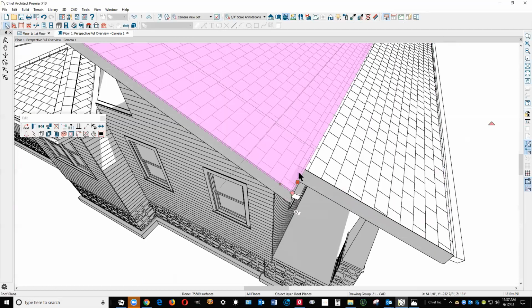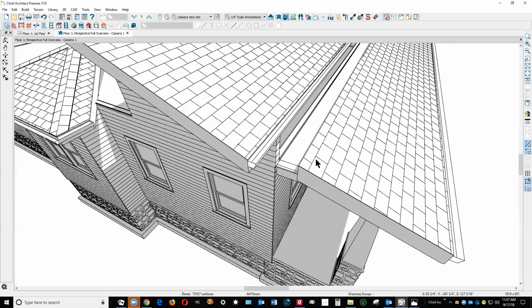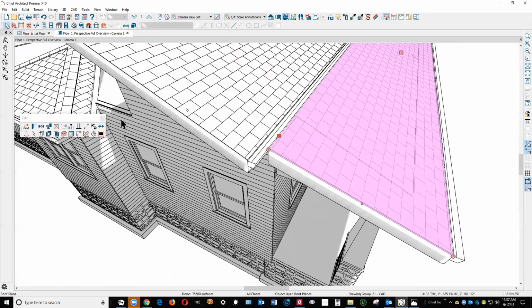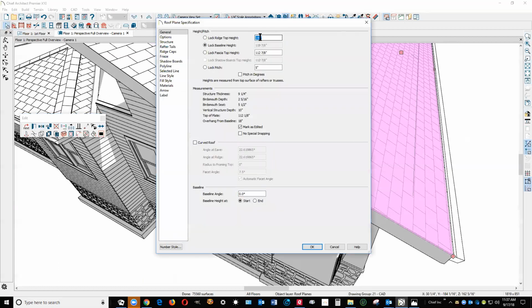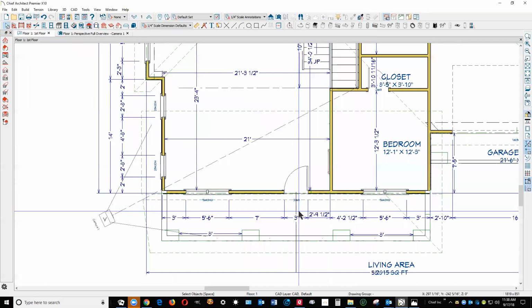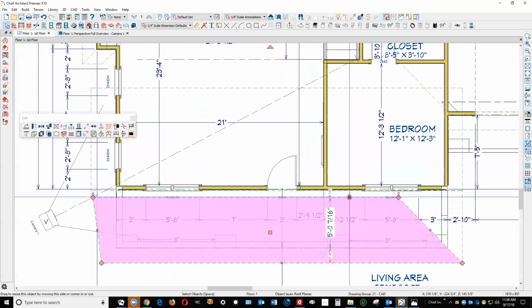Oh, that's kind of annoying. I'll tell you what I'm going to do. I'm going to raise this shed roof right over that wall, and then find out what its ridge height is, 145. I'm going to copy that and make sure that these roof planes are collinear in plan view. I'm sorry, now I have to get that figure again.